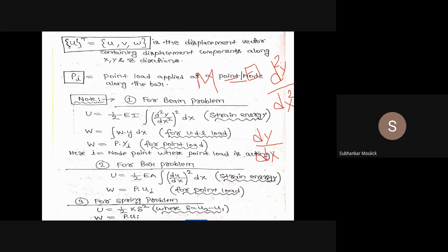I'm talking about moment. In strength of material, when you solve the problem for bending of a beam, if you find out the value of strain energy, that value comes out to be near about M square by 2 EI. So we are converting this term by a differential factor and then integrating it over the entire domain. Ultimately, this equation and this equation both are same. The way of writing is different. Are you getting my point? Yes, sir.